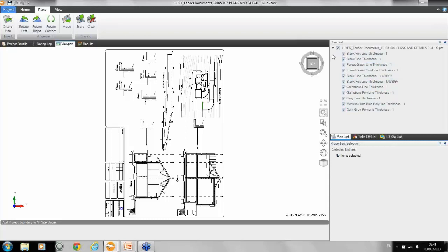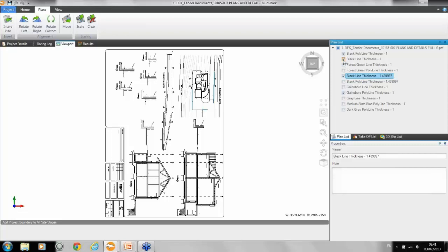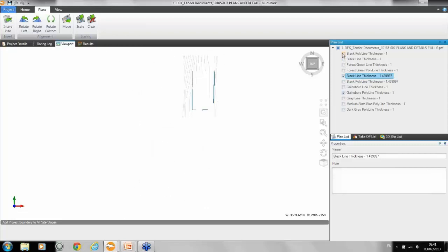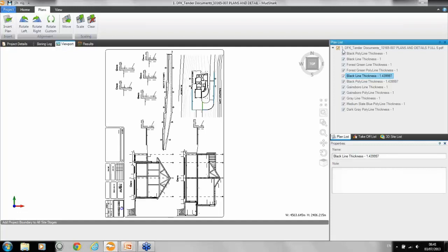So you'll notice here, if you were using an AutoCAD file, you would be familiar with the fact that your layer information appears, and you can use these little check boxes to hide and turn off certain information on the file. So you can actually use this to turn off information on the CAD file. You can see there your existing layer, or if you want to turn on everything, you can do that easily as before. So the software automatically creates layer information if none exists already.